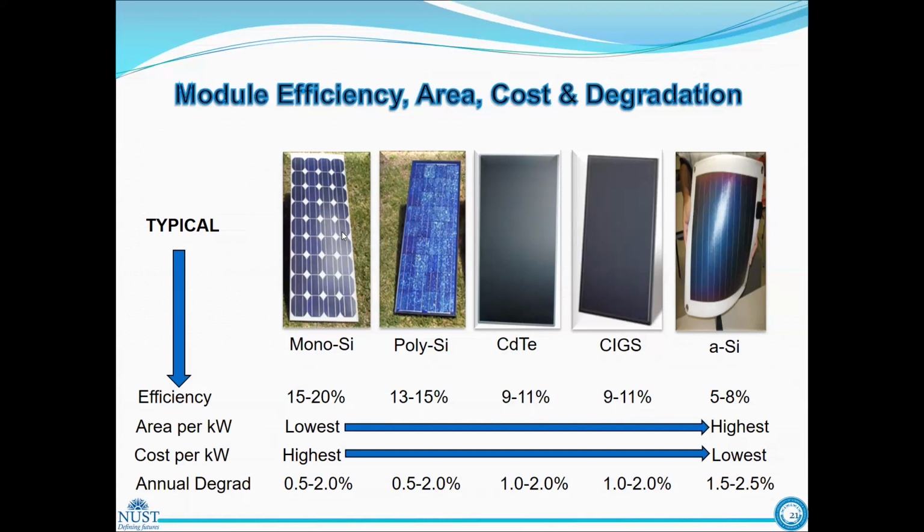But even then we will have some rise, but of course at higher cost, and if we are not achieving the maximum, then this will not be beneficial. We must make changes. We can put some white paints, some reflecting paints on the surfaces which are beneath photovoltaic modules, not the back side of the modules.